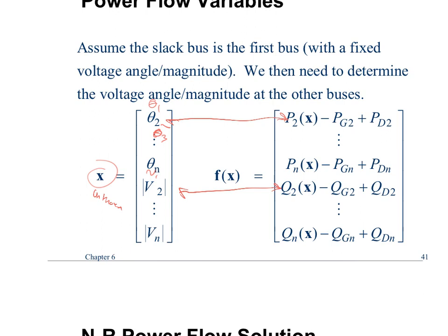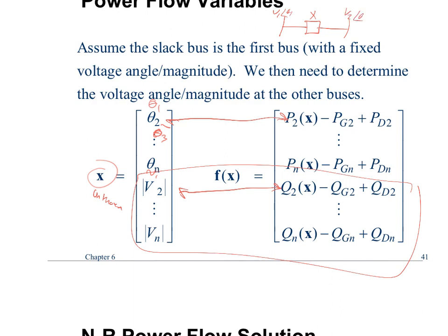That's actually shown in more detail here. From our transmission lines, if our X over R ratio is high enough, if this is V1 at an angle of theta 1 and V2 at an angle of theta 2, I can tell you the direction of power flow. If theta 1 is higher than theta 2, then real power flows from bus 1 to bus 2.